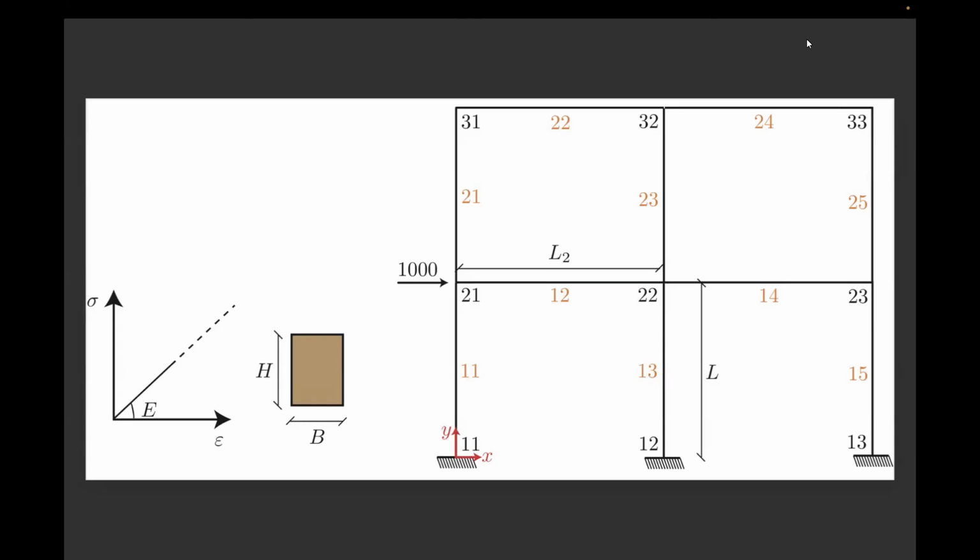You can see here 1, 1 is representing the first column, 1, 3 is representing the second column, 1, 5 is representing the third column. Obviously, in the notation, the first number is representing the floor. The second number is representing the location of the column. Similarly, we have the beams, so you're moving from 1, 1, 1, 2, 1, 3, 1, 4, and so on. And similar in the second floor. In this way, you have a clear understanding, and you can build in a parametric way, which means, in other words, to build a series of for cycles to define your structural system.